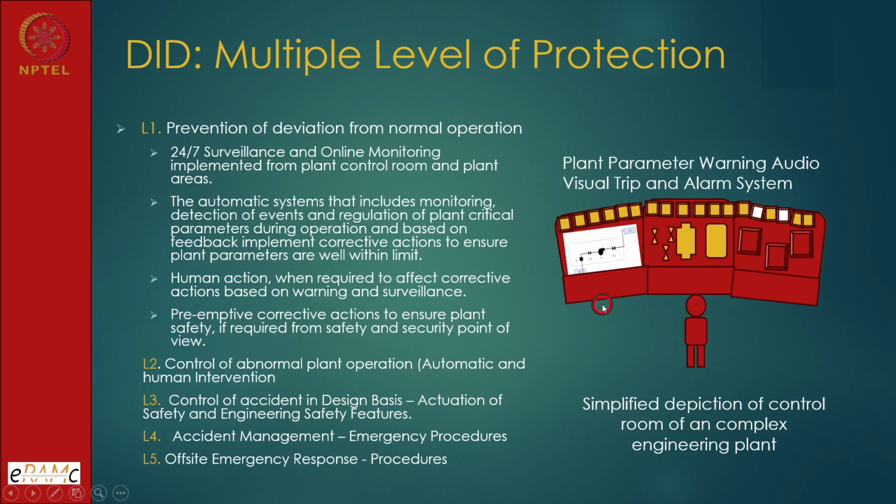So automatically the on-site DC generator set will start. They will not require any special human intervention, and they will operate, the plant will be shut down, and the cooling system required in shutdown mode will be operating. The operator's role essentially remains supervisory unless some deviation has occurred, and he is there to control those deviations based on these signals and the information coming to him.